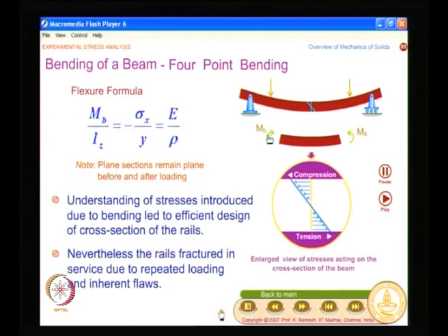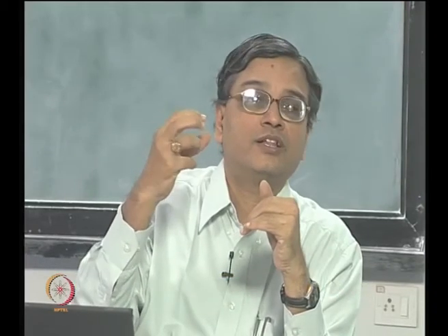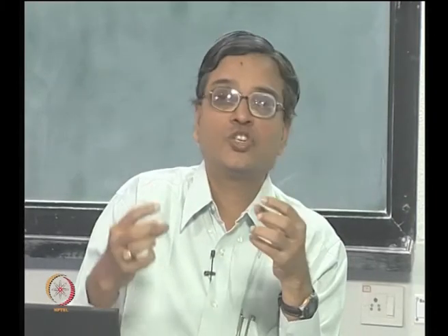So in a first level course, you learn how an axial member supports load. That is why a lot of trusses are used in stadiums and very large halls. You effectively utilize the role of material completely, because all the material contributes to load sharing. The moment you come to bending, you understand that stress varies linearly, so the inner core is not contributing to load sharing.